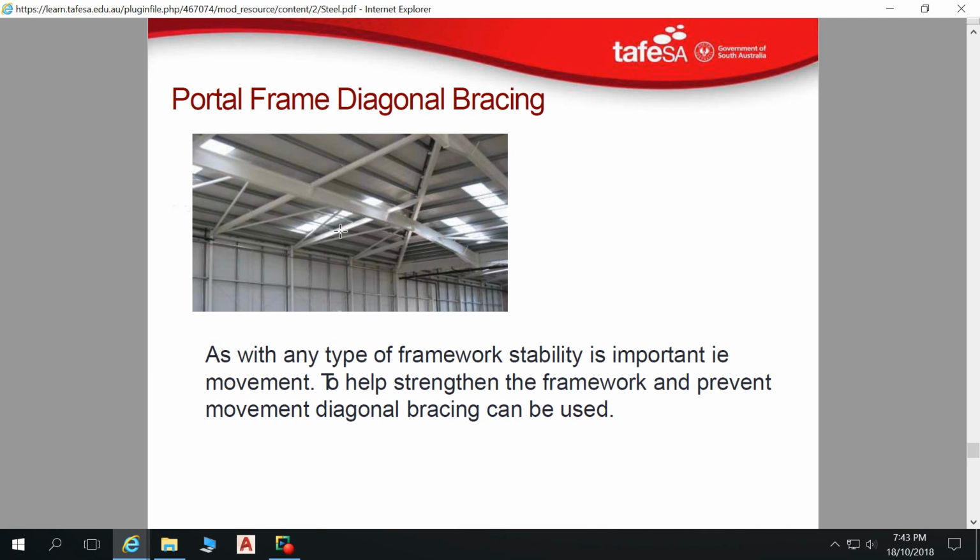So sections of equal angle, but like your steel rod bracing, you've got to get your fixing points correct with that. Your equal angle, that's not going to sag. So it's got to be straight, and then you fix it in there, and then as soon as it's fixed in there, because it's not sagging, if you get any actions on there, it gets activated. It's fine. It's just your rod. You've got to be careful with your rod.